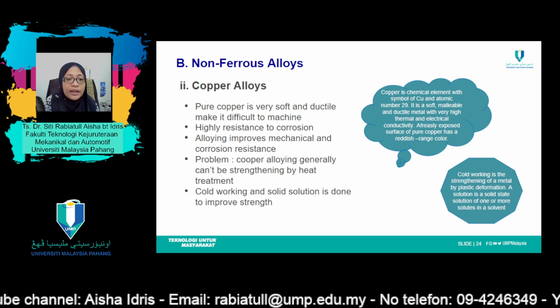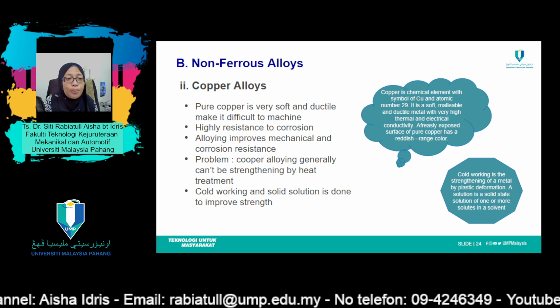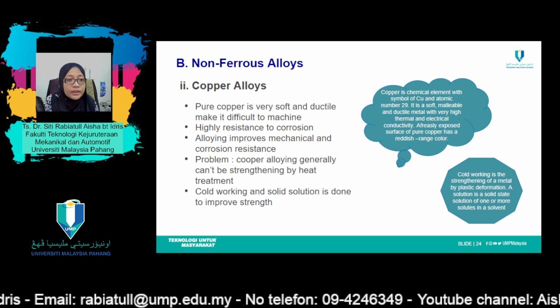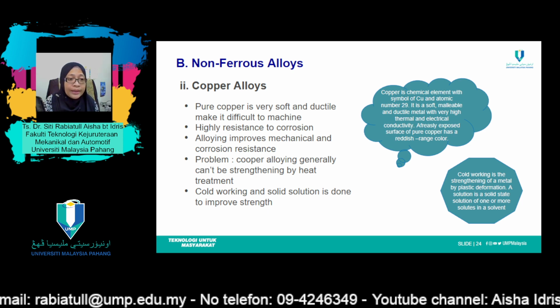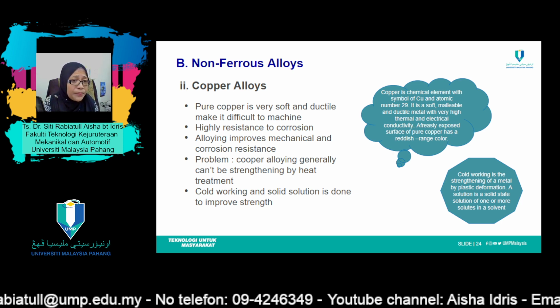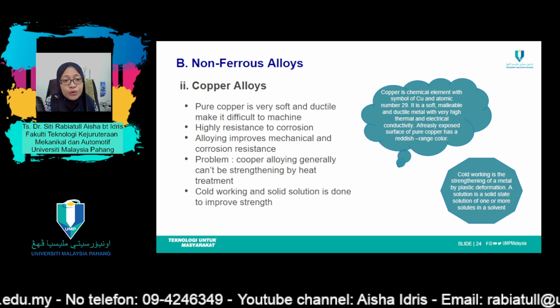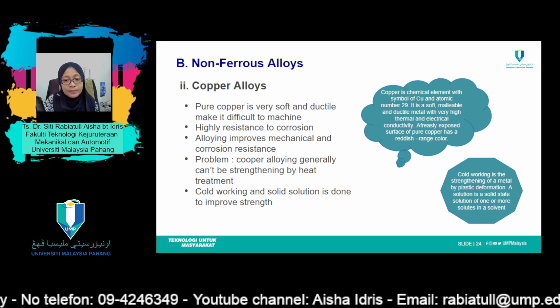The mechanical and corrosion-resistant properties of copper may be improved by alloying. Most copper alloys cannot be hardened or strengthened by heat treating procedures. Consequently, cold work and solid solution alloying must be utilized to improve these mechanical properties.